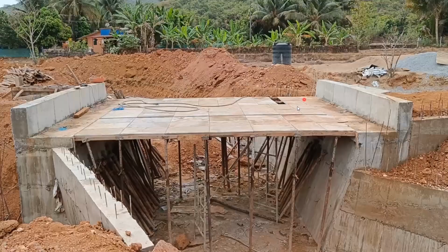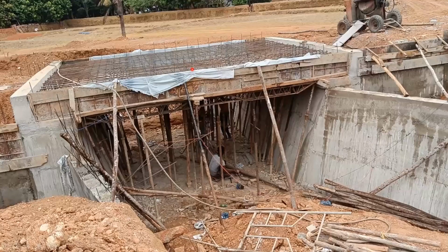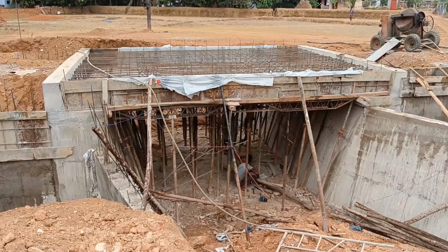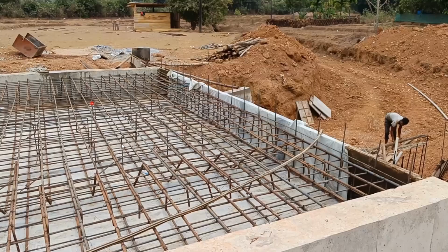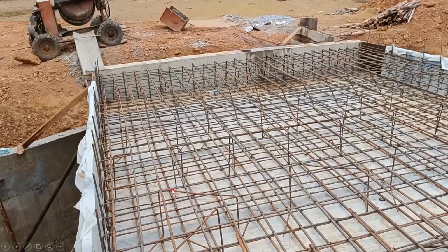Okay, and once that is done, next what we are supposed to do exactly? Next we are supposed to put the reinforcement. Okay, so again after that, if you do the concreting, this will become your slab. So all this has been done, reinforcement has been tied. Again here the same thing will happen. We have made use of a 25 diameter bar. In this way we have arranged it. Again we have a bottom mesh and we have a top mesh. Bottom you can see horizontal and vertical, we have given a chair, and then again the top portion we have given. So in this way everywhere we have done.